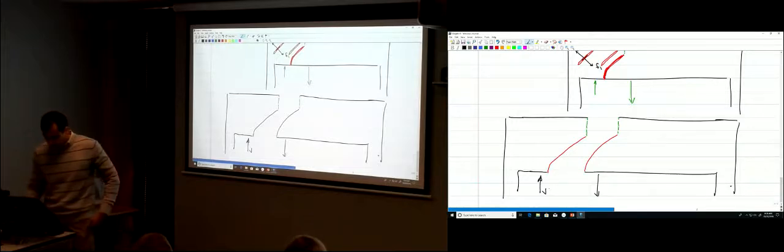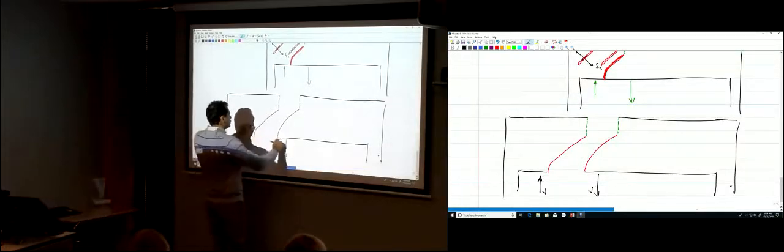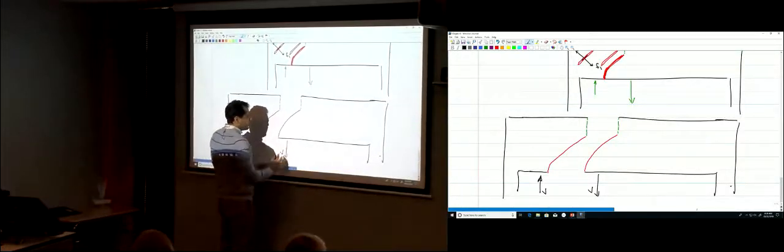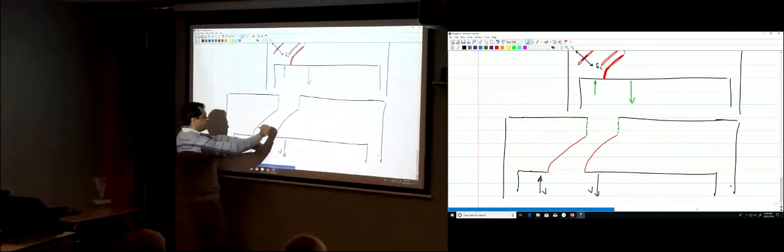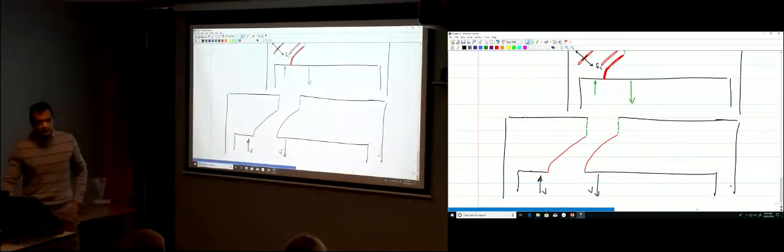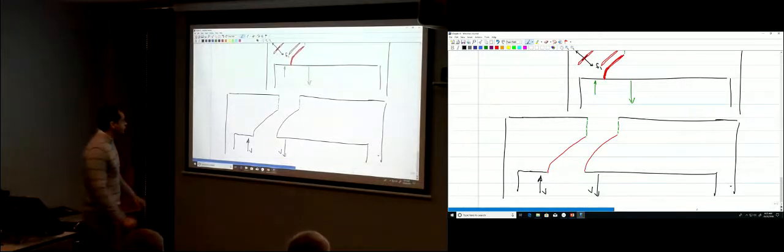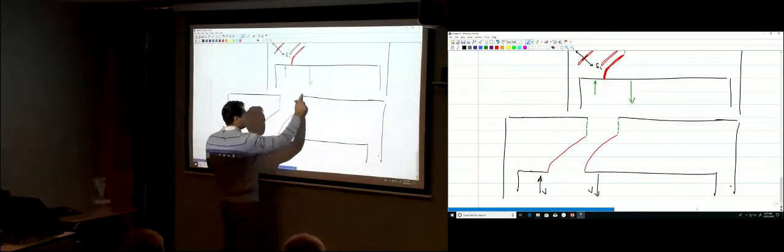The shear force V. I just want to make sure that this surface has enough resistance to prevent the beam from breaking on this surface here, okay? After developing this flexural shear crack, okay? So what is resisting this shear force along that surface?